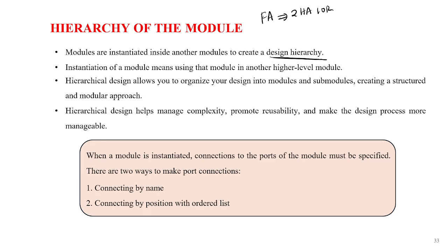To write the code for a full adder, first you write the code for the half adder and instantiate it 2 times, and one OR gate is used. Similarly, for a ripple carry adder, first you write the code for the full adder and instantiate it 4 times. That is nothing but instantiation.